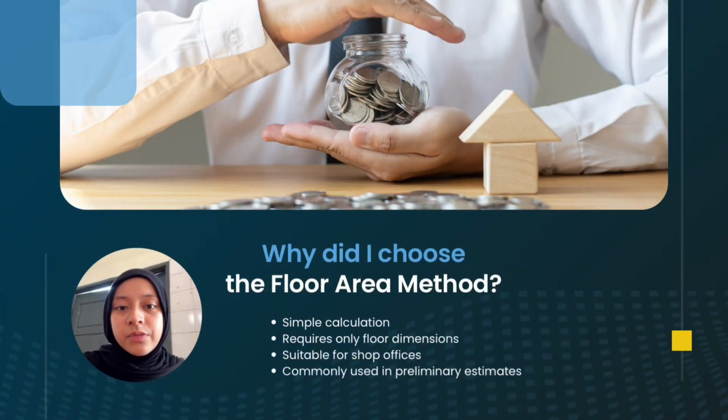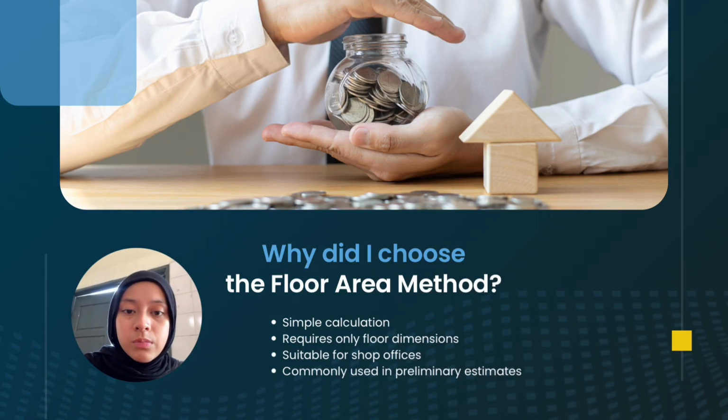I selected the floor area method because it is simple to apply and only requires the building's floor dimensions. Since this project is a shop office, the floor area method provides a reliable preliminary estimate without requiring detailed quantities.